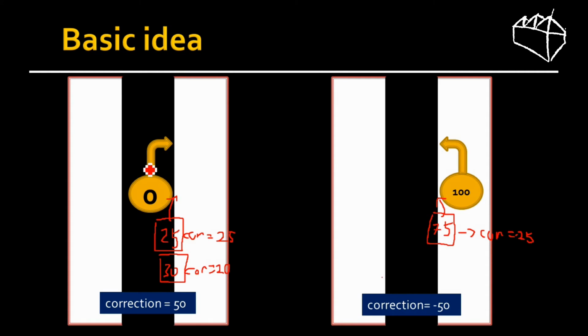What it actually does is it takes the value from the color sensor and computes the distance between your sensor and the edge of the line. So for example, here it's 0. So the distance between your position and the position where you want to go is really high, so it has to turn more.